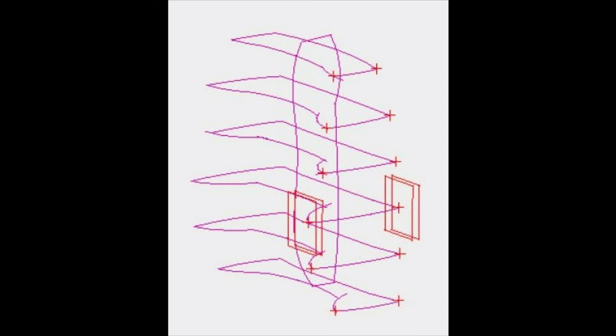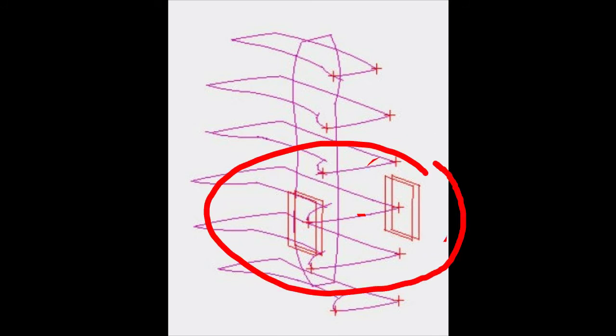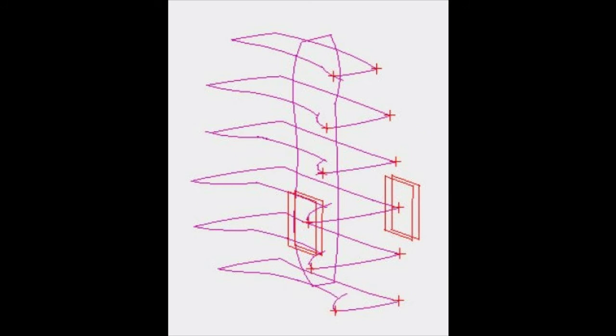Since the surface needs to be extended beyond the intersection point, create a plane that is 10 mm parallel to the plane we already created previously. The planes previously created. All these steps are shown in the image. You can see that image on the screen.